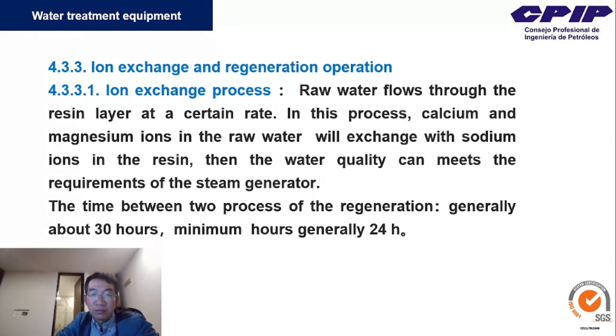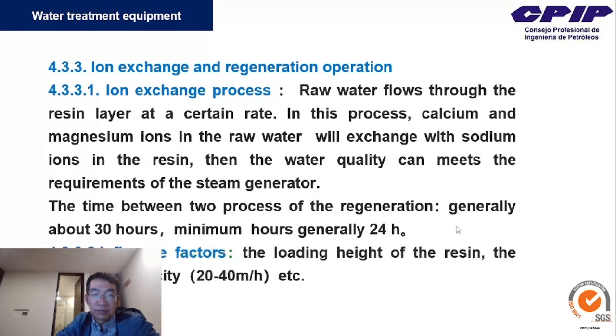The time between two regeneration processes is generally about 30 hours. The minimum is generally 24 hours. And the influence factors are the loading height of the resin, the exchange velocity, and so on.